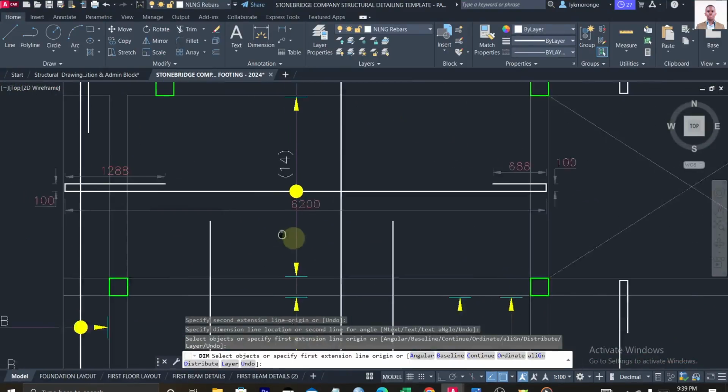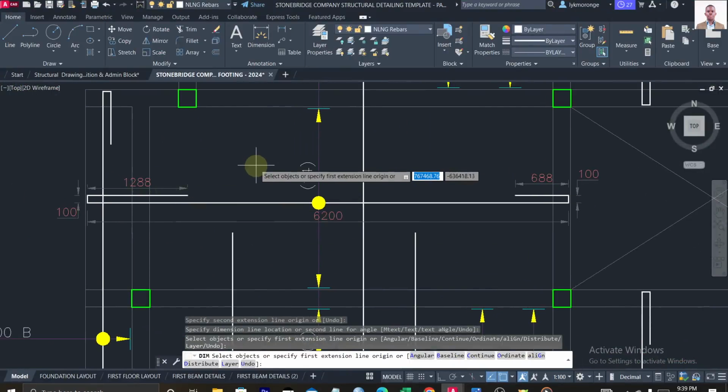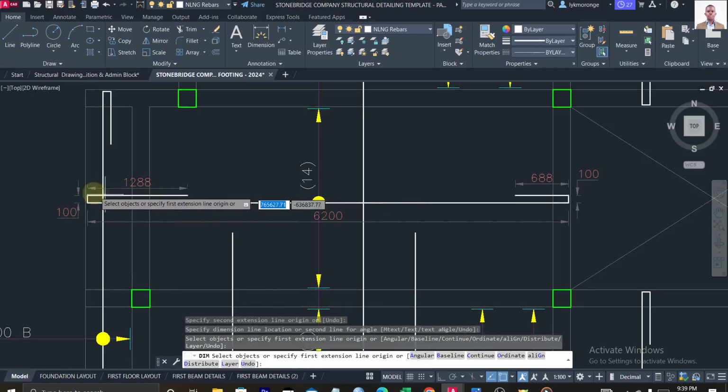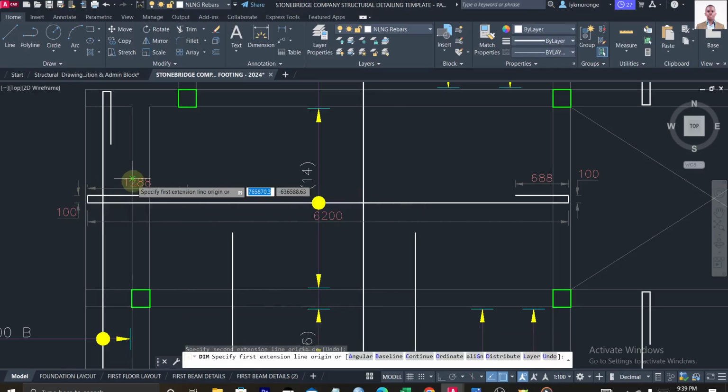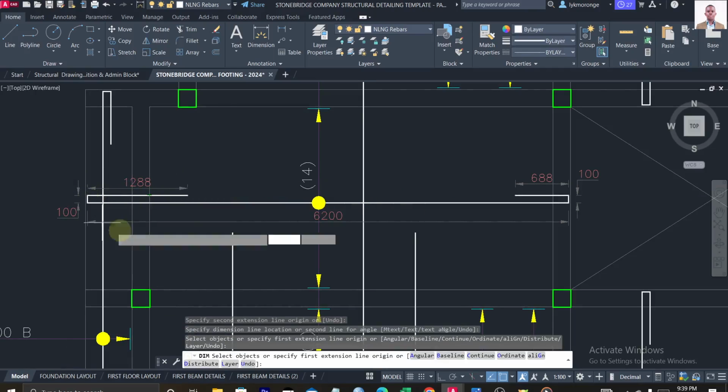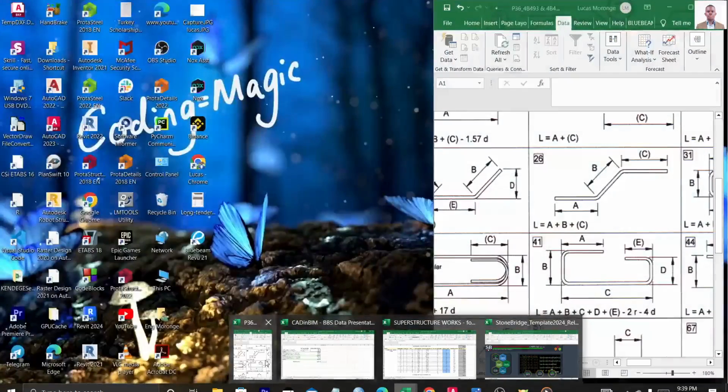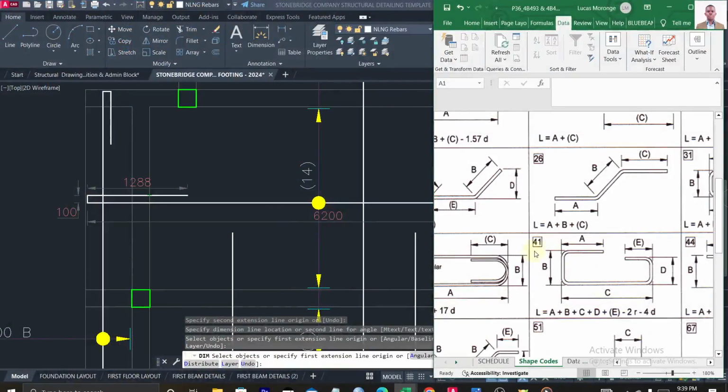maybe for a DWG, dimensions will be given, but if they are not given, you can always estimate, or just dimension them. So this shape, A, this B, let me show you again so that we are together. This length here, A, will be 1285, so 1290, because you have to give them in multiples of 5 according to the BS.